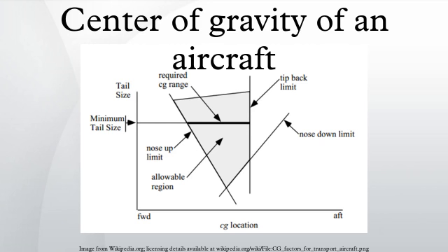Because the burning of fuel gradually produces a loss of weight and possibly a shift in the CG, it is possible for an aircraft to take off with the CG within normal operating range, and yet later develop an imbalance that results in control problems. Calculations of CG must take this into account. Here's an example of a Piper Mirage with too much weight in the back of the aircraft that results in the takeoff CG within limits but the landing CG is aft of the CG envelope limits.